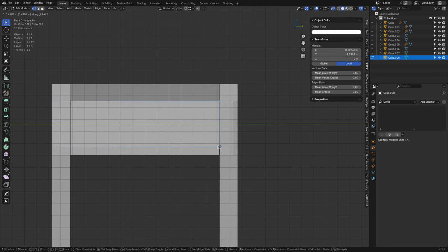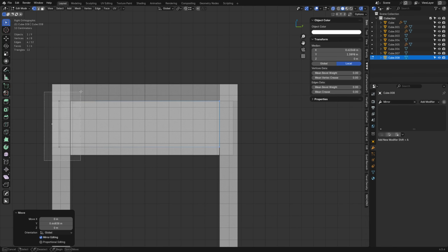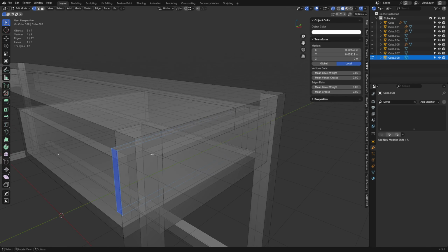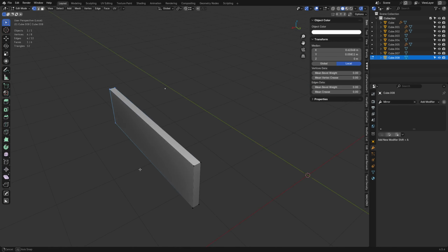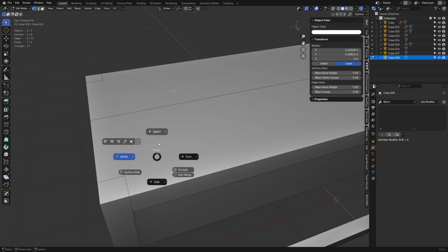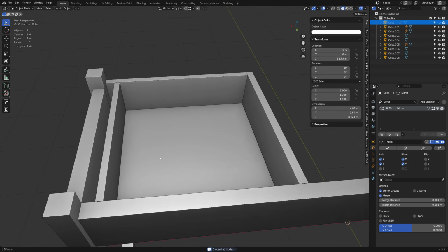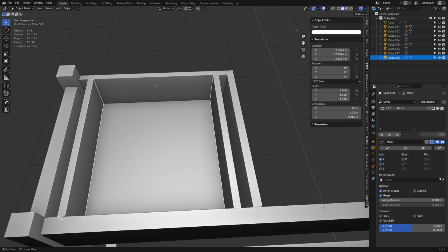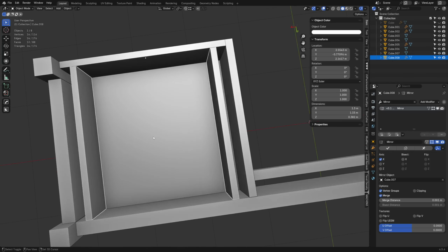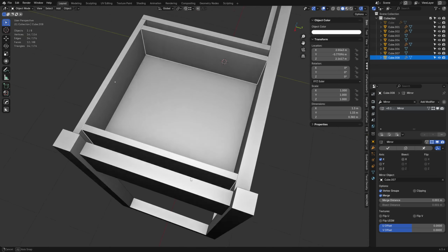I'm just going to go ahead and bring those back, and we might as well align them all the way to the back. I don't see why not. The front one here already aligns to the drawer, or it should anyways. So we should be good with that one, right? The way we did this, remember, let's hide this guy real quick so we can see what's going on. Press H. This one here, we set the origin right off the bat, remember? That was so it would still have the same origin, so we could do a mirror. And if it didn't have the same origin, we could just pick the front of the drawer maybe, right? So now we get this set up here, which works out pretty well.